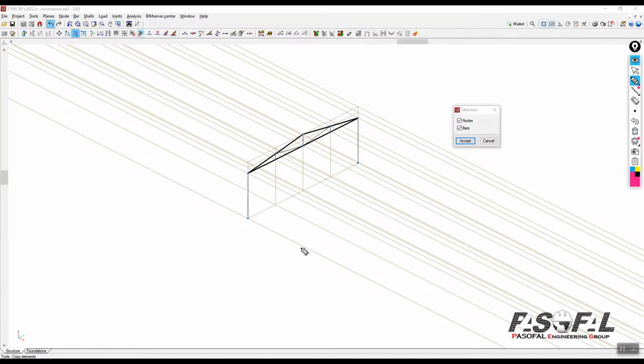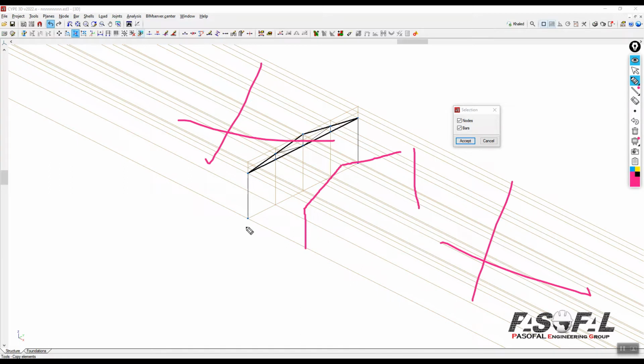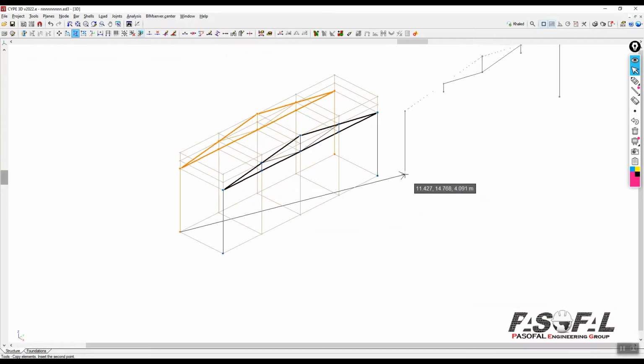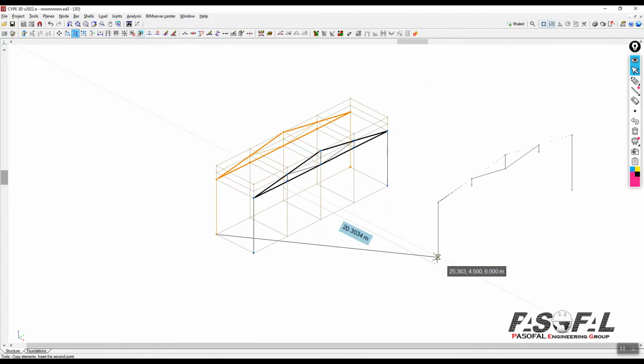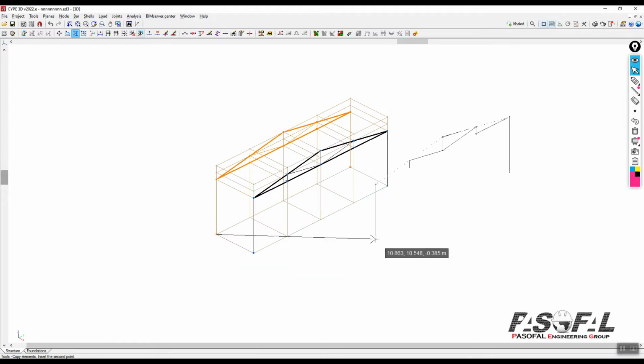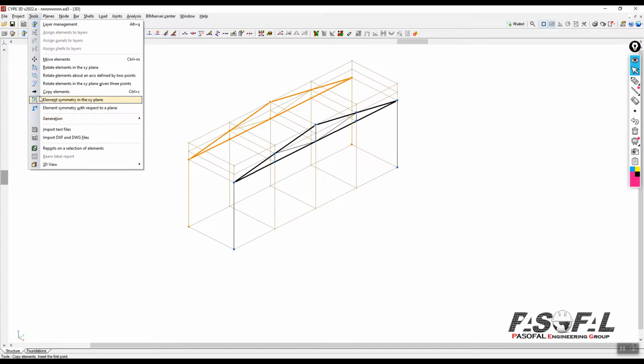As soon as I added the copy, for example here, all this reference line will be removed, because again in the x direction the software understands that here it is the border of this structure or model. It is a very good thing. So let me once again go to copy. Again, select all the members. If you look at the instruction at the bottom side, you will see that it says to select a group of elements. I selected the group of elements and then right click, and then select the reference point and come in this direction, and write 5 and then enter. You see here the reference lines that previously we had in the X direction, all of them are cut, because the software understands the geometry and boundary of the model. So it is the way that you can use the simple copy option.